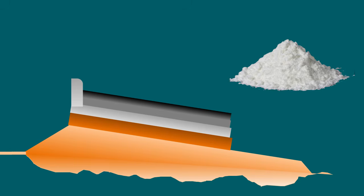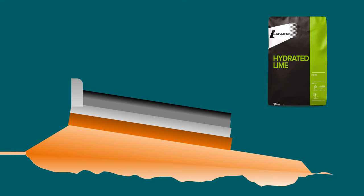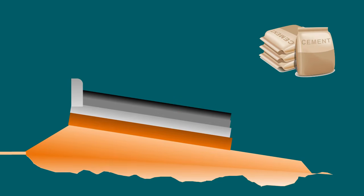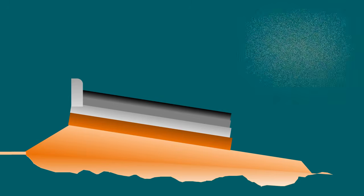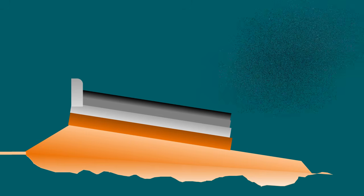Around 4 to 5% of filler materials are used to get a smooth finished surface. In projects like airport runways, lime powder or cement is used as filler material in order to ensure a 100% smooth top surface. The percentage of binder material, that is bituminous content, in WC is slightly higher than in DBM, and this layer is always used as a single course to a maximum thickness of 100 mm.